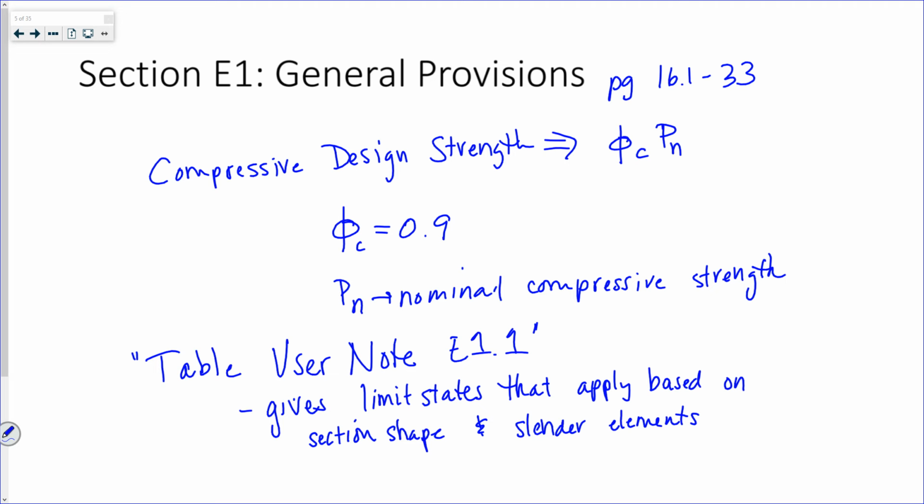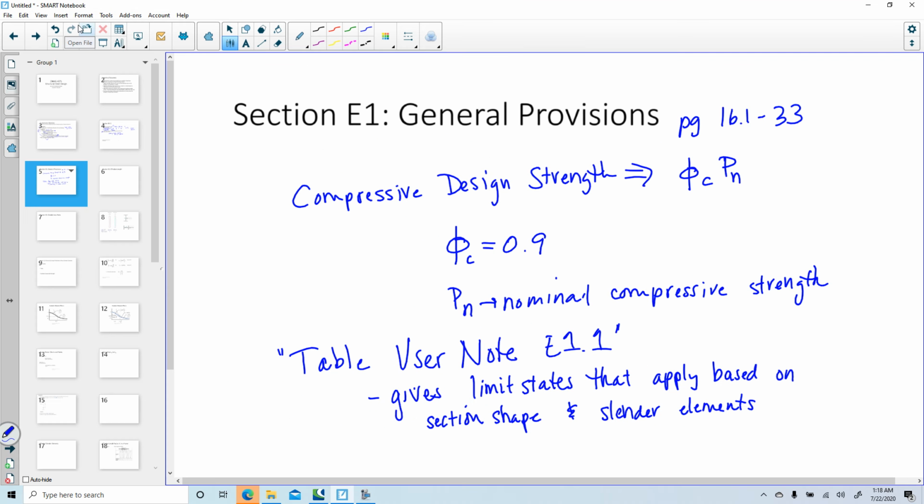And it has been determined that certain limit states might not apply to all the sections, because, for example, you're probably not going to have a torsional buckling in certain shapes. Anyway, there are certain shapes that just aren't going to lend themselves to certain types of buckling, is what I'm trying to say. So if we look at that, let's see.